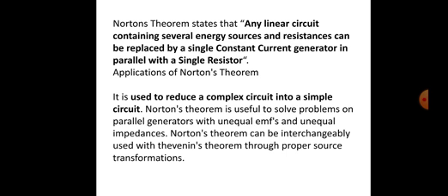Step 5. Draw the Norton equivalent circuit with the Norton current source in parallel with the Norton resistance. The load resistance reattaches between the two open points of the equivalent circuit. Analyze the voltage and current for the load following the rules for parallel circuits.